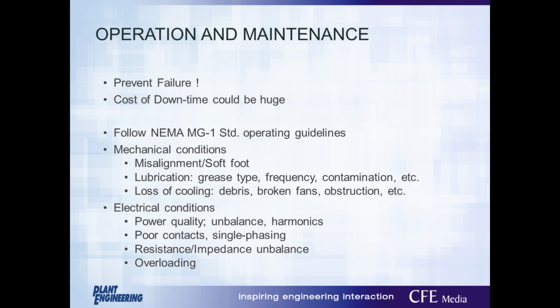Grease both the drive end and non-drive end bearings, and make sure the grease nubs are clean before adding the grease so you don't get contaminants in the grease. Most motors today use Polyrex EM. You can't assume that for all motors. That's just typically the most common grease for new motors. So it's good to keep some tubes of that around if you don't already have some.